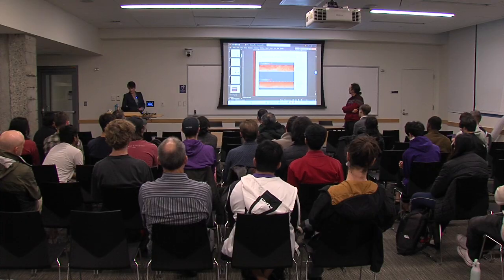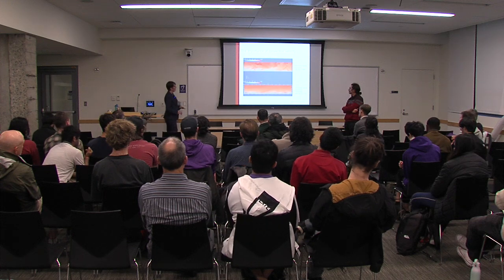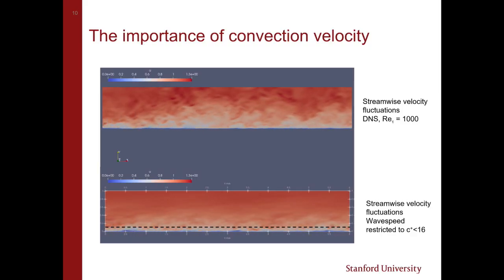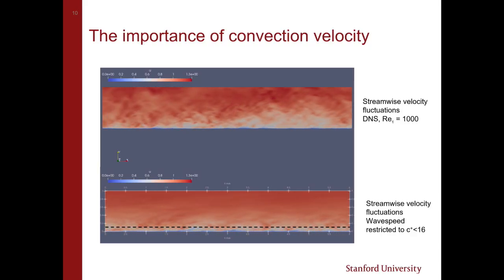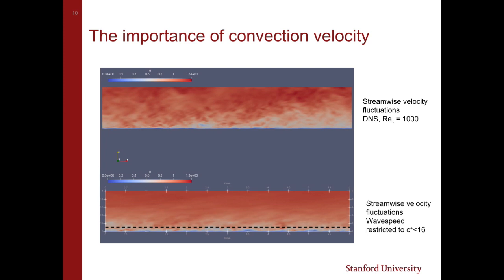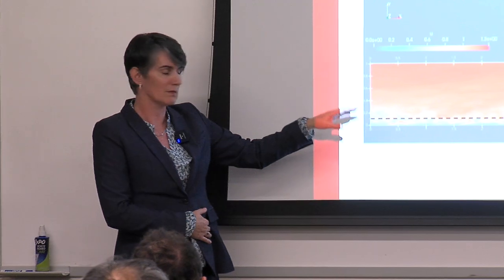So, oops, I get there. Yeah, here. So this might be your first grid point at y+ of 100 in the channel. So everything below this, all that space-time dependency that you're seeing, gets lumped into a way to basically impose the wall, get the right wall shear stress.